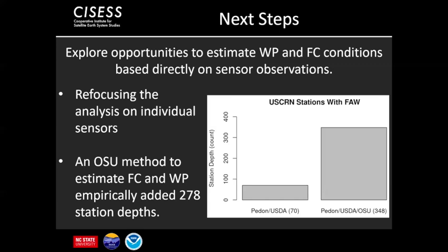I'm actually a big proponent of the -10 kPa field capacity because that's what we see from a lot of field data. But beyond that, have you thought about doing any comparisons, especially if you have bulk density and texture data for your other sites that you don't have the lab data, by doing some pedotransfer functions like Rosetta or something and comparing those estimates as well, along with some of the stuff that you're looking at to see how well those match with what you're seeing in the field?